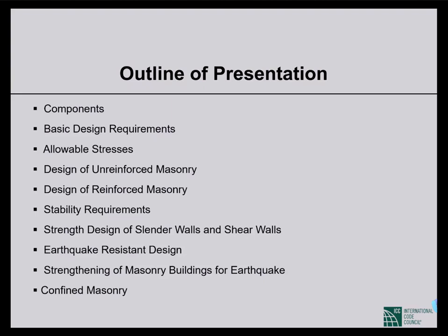Usually this type of construction is very, very vulnerable to earthquake. This type of mixed construction, this frame construction and this load-bearing unreinforced masonry, are not compatible, in the sense that frame construction is quite flexible compared to unreinforced masonry.